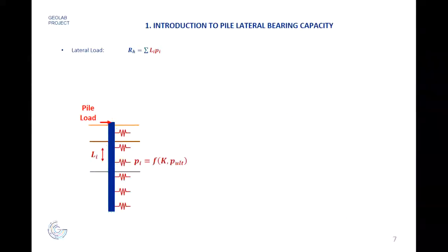Okay, so I spoke about vertical loading, but we may also have horizontal load. It's the case, for instance, if we design a bridge whose piers are founded on piles. We may have accidental or exceptional horizontal loading due, for instance, to the braking of a train that passes on the bridge. And so we have to take it into account and design the piles correctly.